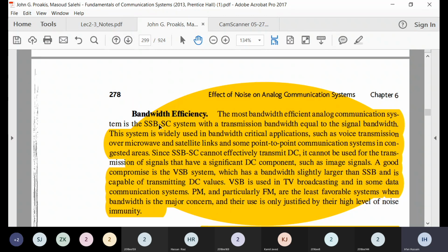But the problem with single sideband suppressed carrier, if you remember, is that once the signal is modulated, the actual bandwidth is 2W, but we just take half of that, 0 to W. But actually there cannot be an ideal filter that takes from 0 to W. Some of the components around 0, or from FC to FC plus W, which now come at FC, will not be transmitted because of filter limitations.